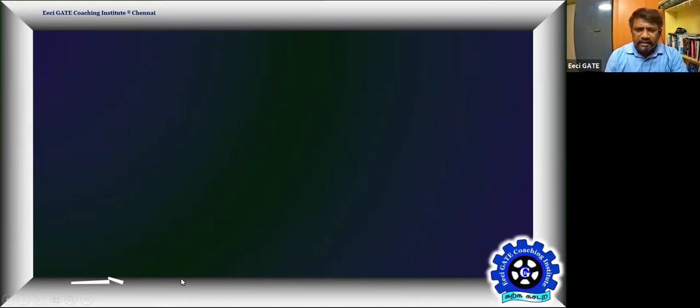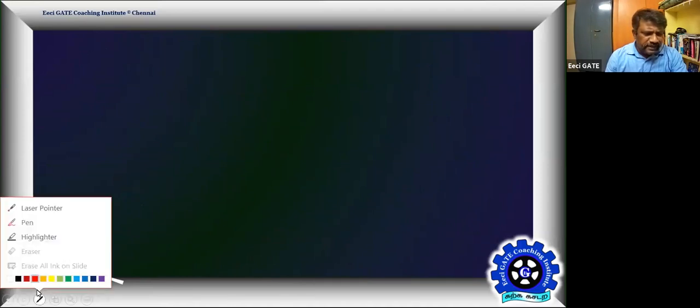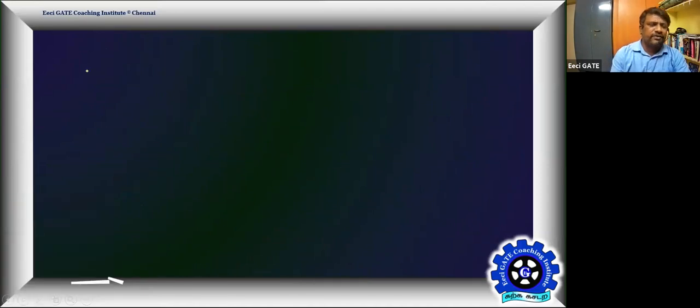We may think of smartly answering the problem using the ready-made equation for a full bridge: V naught of the bridge is equal to E into delta R by R. Even though it is current excited, we can calculate E, the voltage across the bridge, which is the input voltage applied to the bridge. Then we can calculate delta R by R. But the big question is which delta R to consider.